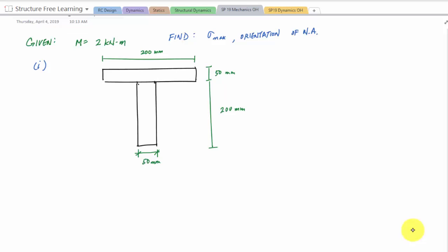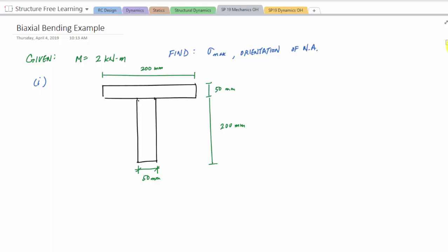And in this video, we are meeting to do an example problem with biaxial bending or an unsymmetric bending problem. And here, the unsymmetric bending equation, because you have bending about two axes on the cross section, this normal stress is negative Mz y over Iz plus My, a distance z over Iy, right here.